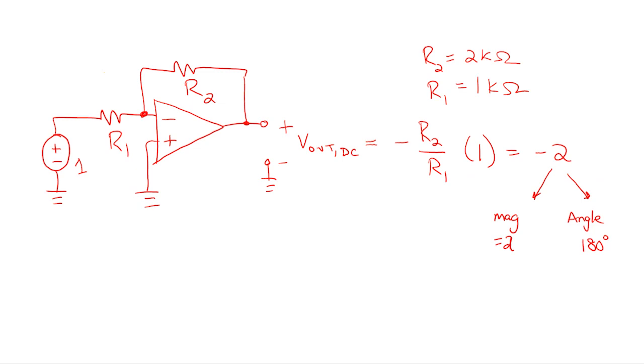But technically phasors apply at any one frequency. Phasor analysis, impedance analysis always applies. The frequency in that case is DC in problem one. I only have resistors, but you were still basically doing phasor analysis in Circuits One and just didn't call it that. Technically it was the same thing, right?